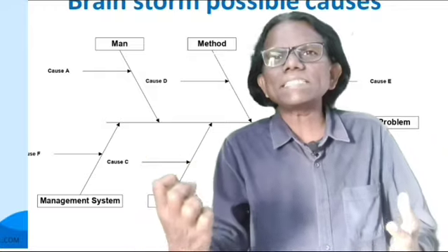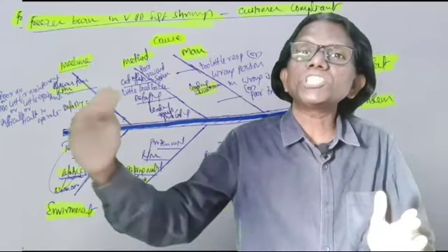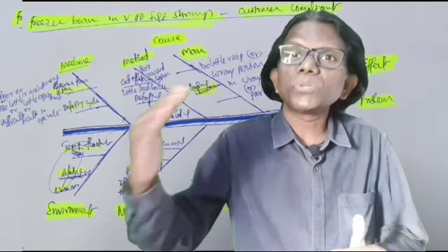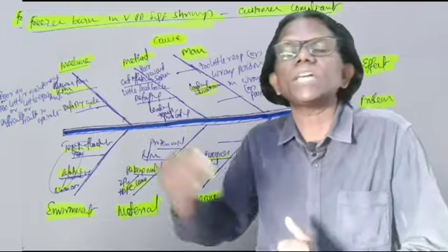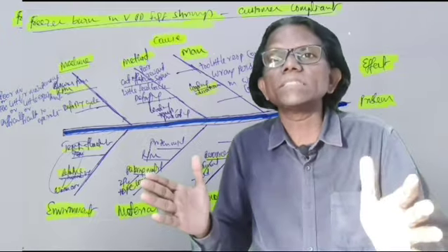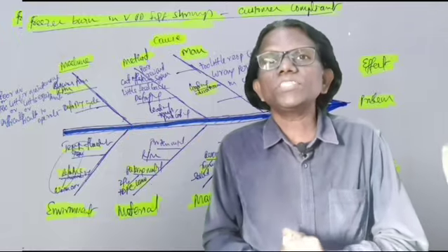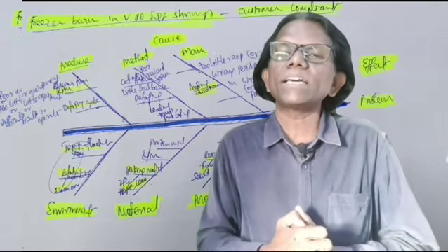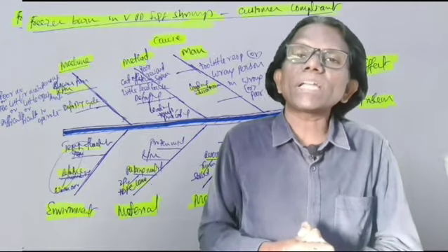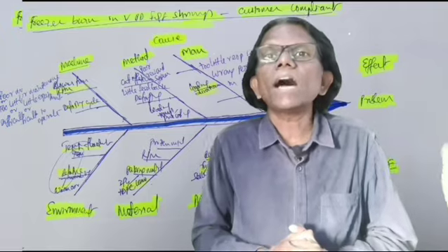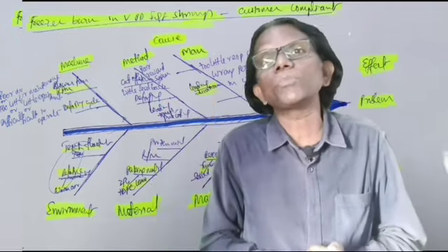So what is your method? At what temperature? The pre-cooling method, and you also have to justify the loading duration. Loading duration and pre-cooling before loading the cargo, and cold storage temperature also, door openings, defrosting time. These are all things you have to include in the method. Without proper pre-cooling of the container before leaving the factory, or if the proper temperature is not attained in the container, or for end-to-end monitoring, do you have the data logger in the container?